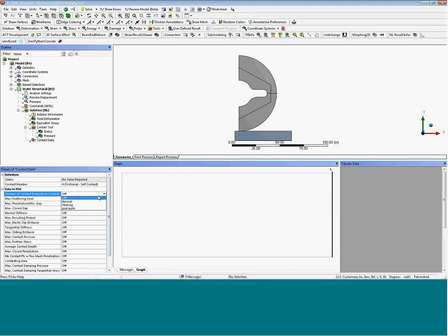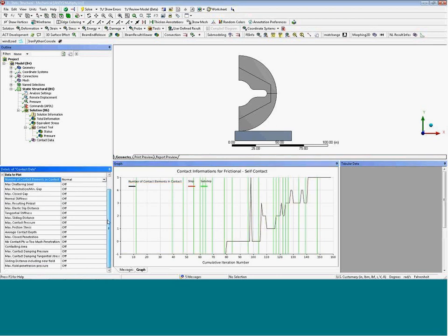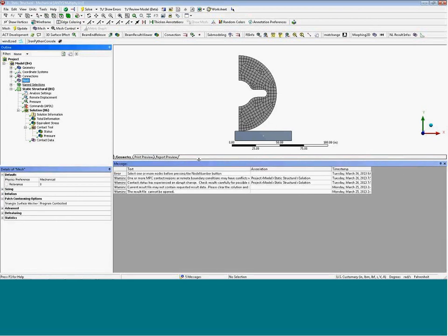through that. And maybe you put in number of elements in contact in the normal direction. So you can see here, that's the number of elements. So then at the end, we get about 5 elements in contact. That can track a bunch of different information in here. Other information might be a little bit more difficult to get out, or maybe isn't available at all. So that is another example.